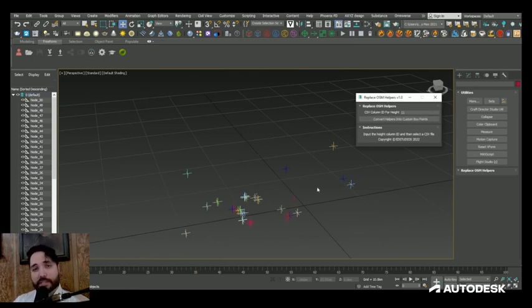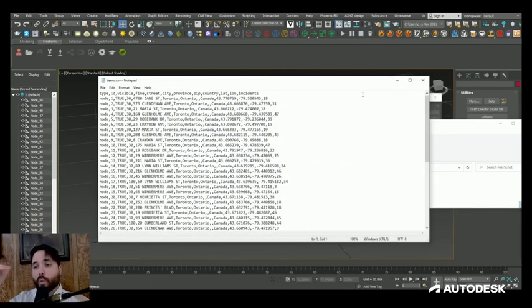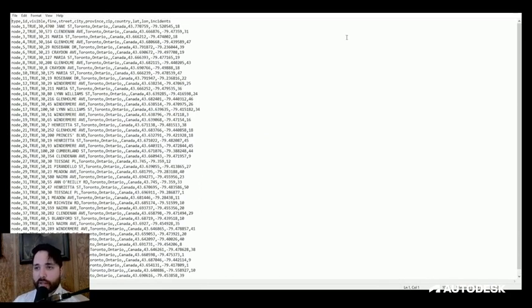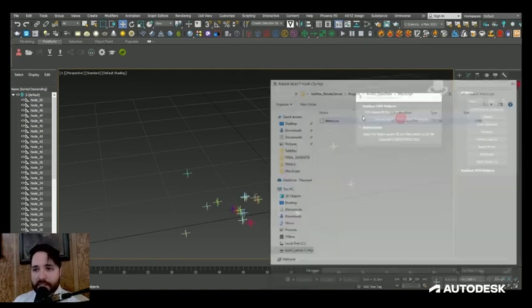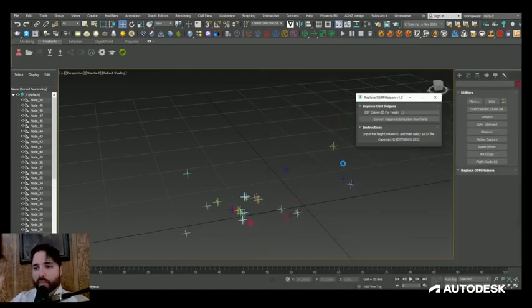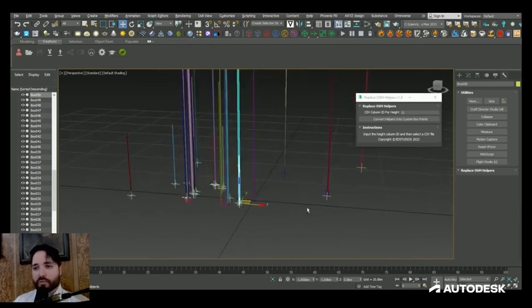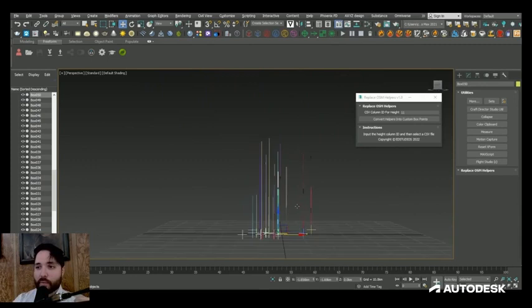I then wrote some MaxScript to create a box tower for each parking infraction location, and have the height of that tower be determined by the quantity of parking fines that occurred at that exact location. It directly reads a CSV file, and it looks at the specific column as reference, and then animates the height of that box over a set period of time. That way I could visualize the parking areas in Toronto that had the most fines, where I'd be most likely to get a ticket if I went there.